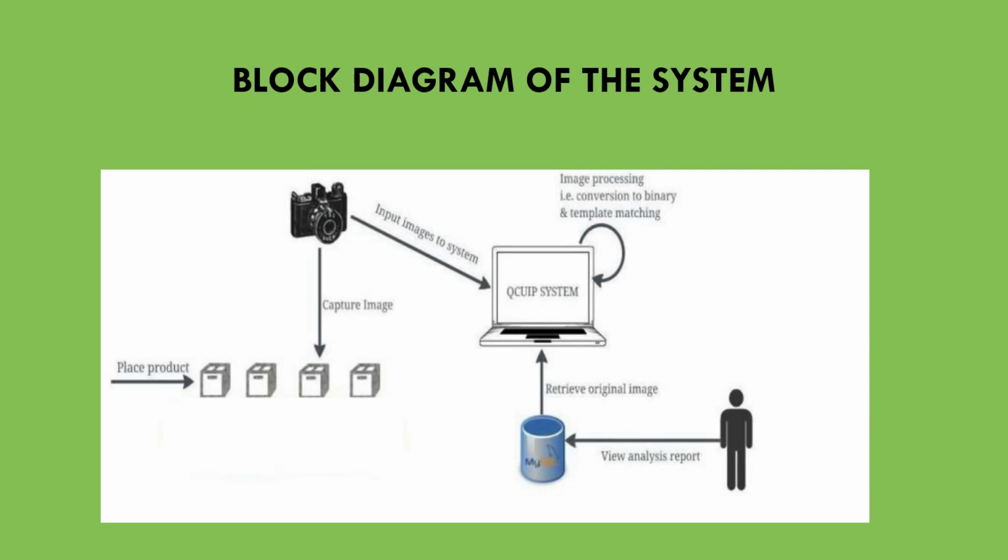Digital image processing techniques are employed to verify almost all the products that are coming out of the product line. This is pursued by taking image of each and every product as soon as it comes under the camera. Captured image is fed to the computer for further processing. The colored image is converted to black and white image and then to binary form. This binary image is then subjected to template matching.